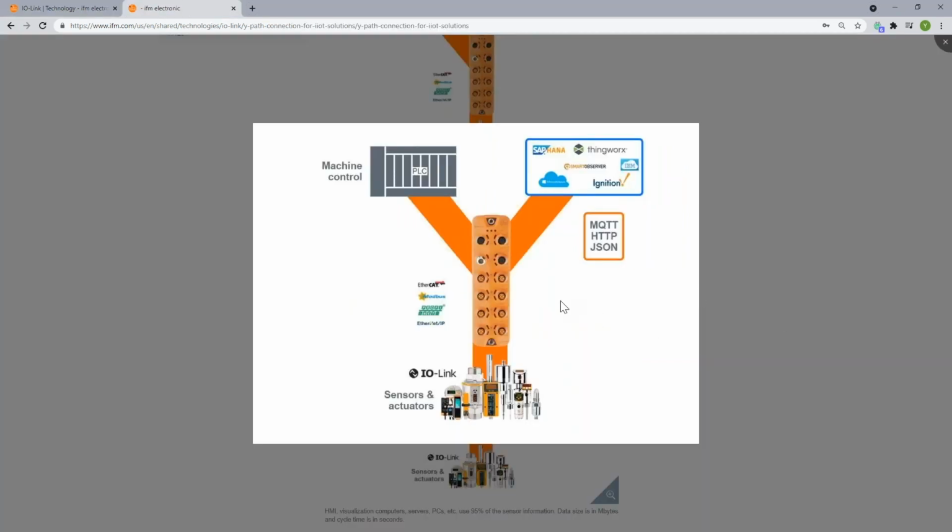And this is the example, just to show the controls architecture. The sensors go into what we call an IO-Link master, which is really just, think about it as a smart Ethernet IO hub. Of course, we are able to pass this information to a PLC because you need the sensors to control your processes. You need the PLC. That's what the PLC does.